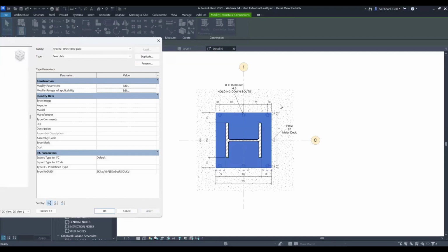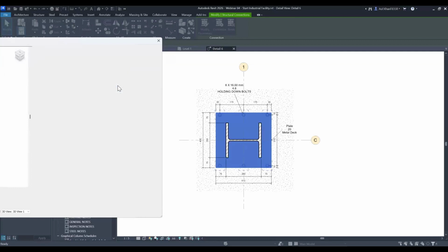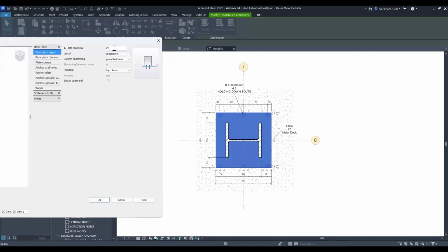As you can see, my plate has shrunk, and that's giving me a real-time update without doing any line work, without doing any manipulation, without the repetitive work that we usually go on doing in AutoCAD. Now automatically it's done. Now the last thing I'd like to show you over here, let's say this plate thickness was changed to 25 mil.